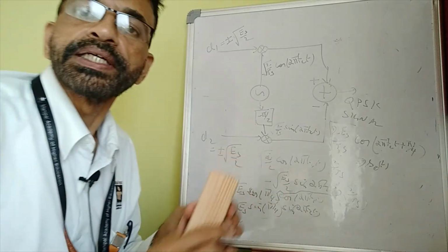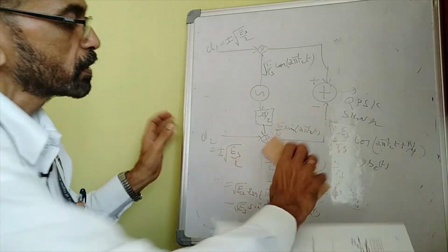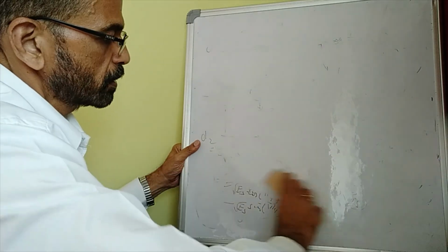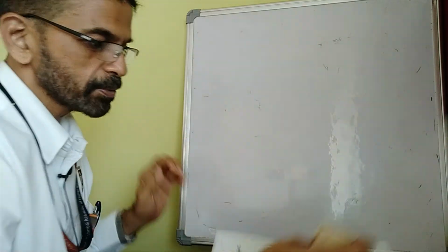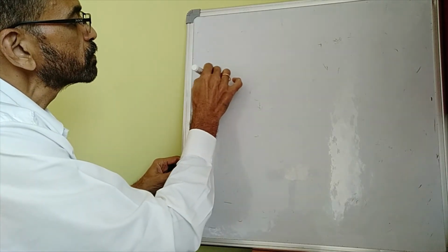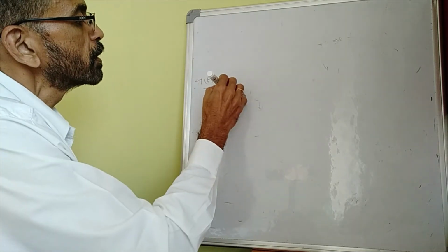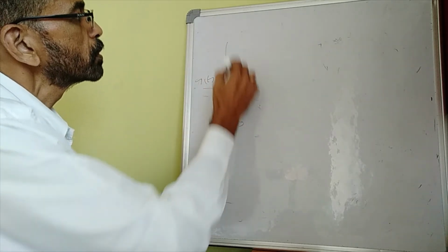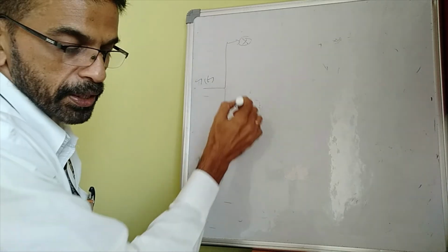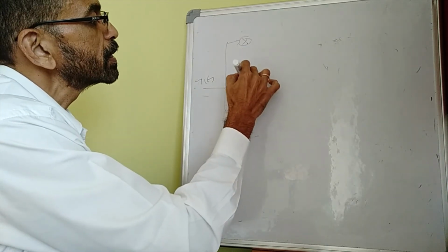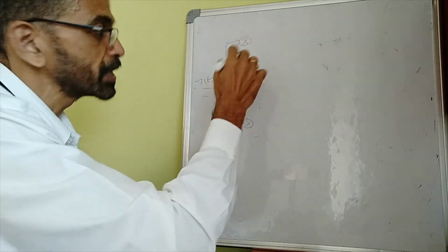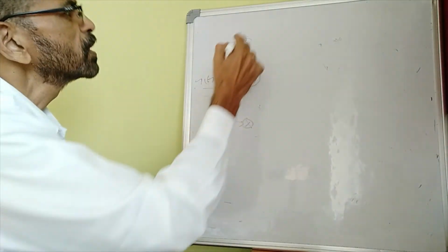Okay, now quickly let us discuss the receiver schematics. The receiver schematic is simple: this is the received signal, split into two. You have to have a local oscillator which is phase matched with the oscillator at the transmitter, because it is coherent detection that we are discussing.